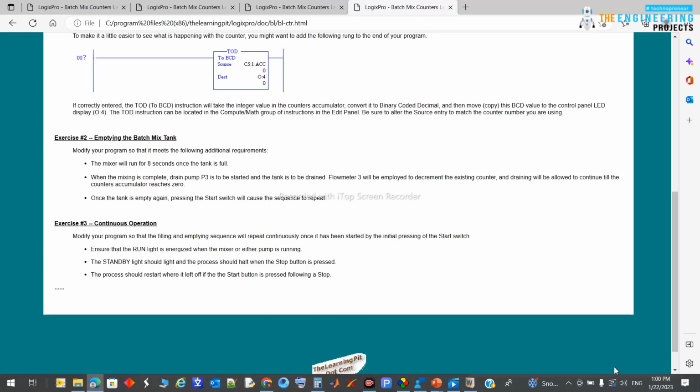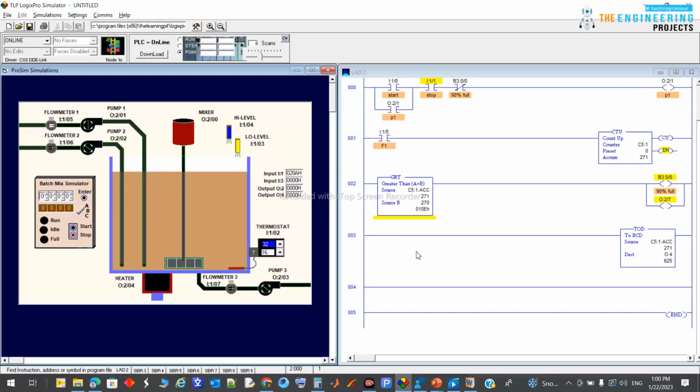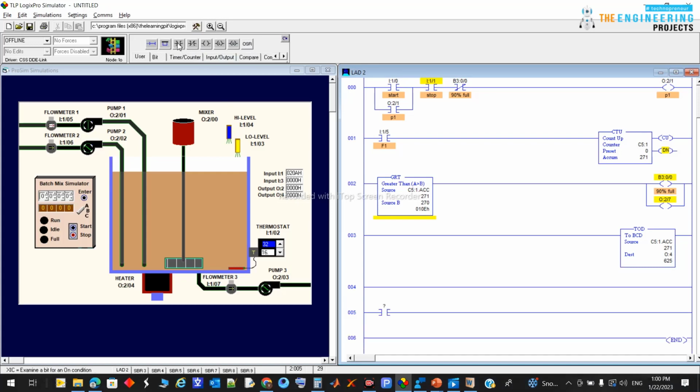Let's go to our program. So here in our program, we need to just continue on this program. So starting from the point we reached, the fall status. So let's go into our code here, adding one. We already have one here. So once we have this one, this one will be the status bit for fall. Once we started this fall, now we need to run the mixer.